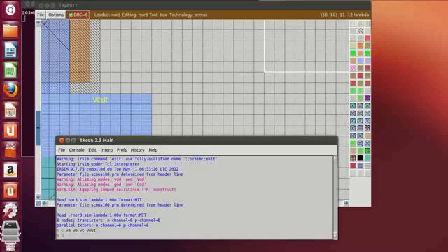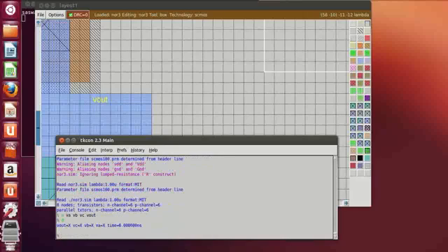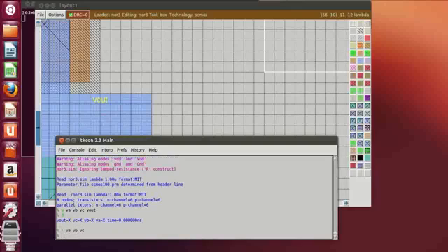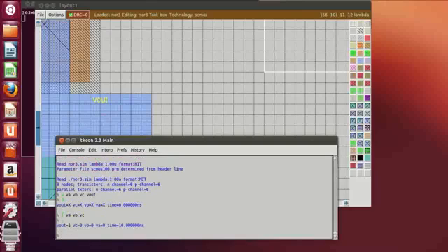Display D, we'll get all the values as X. Then since this is a NOR gate, let's give low value to all VA, VB, and VC. L stands for low and S to create a step function. When 0, 0, 0, NOR output is 1, the invert of the OR. For 0, 0, 0, the output will be 1. For any other values, the output will be 0.